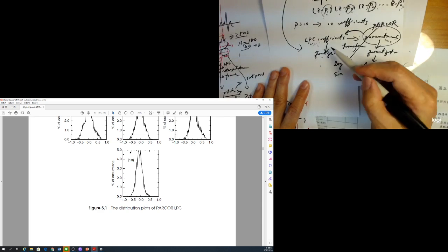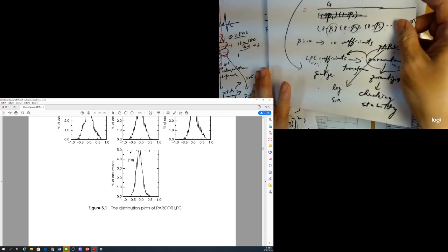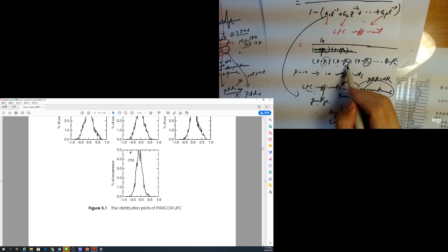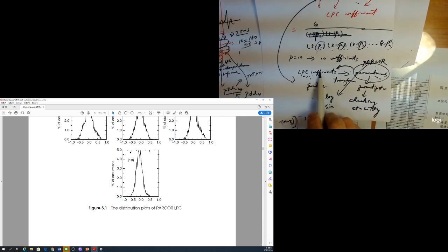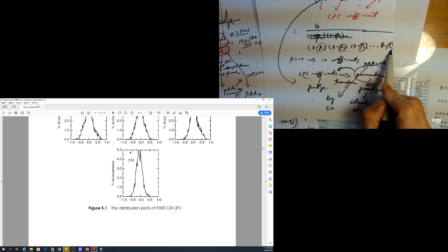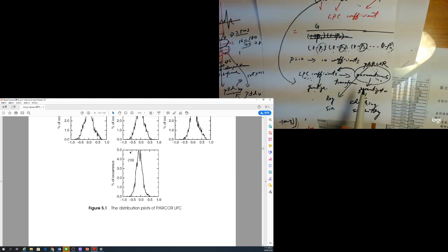we can synthesize back the original signal. So in the first part of this chapter, they talk about how during quantization you can know whether your filter is stable or not. Maybe the original coefficients are not related to your poles, so we have to transfer your coefficients to the PARCOR and make sure the PARCOR coefficients are related to your poles. That lets you double check during quantization whether the original filter is stable or not. That is the main idea here.